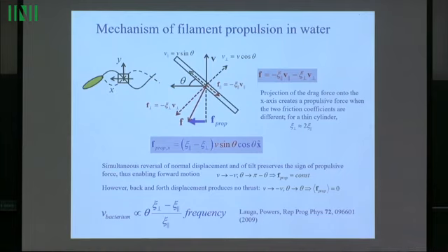So when it moves up and down, the thrust that is produced is still directed in the same direction. And so you look at this formula, you realize that yes, when you change the signs of v and change theta to pi minus theta, your propulsion is constant.